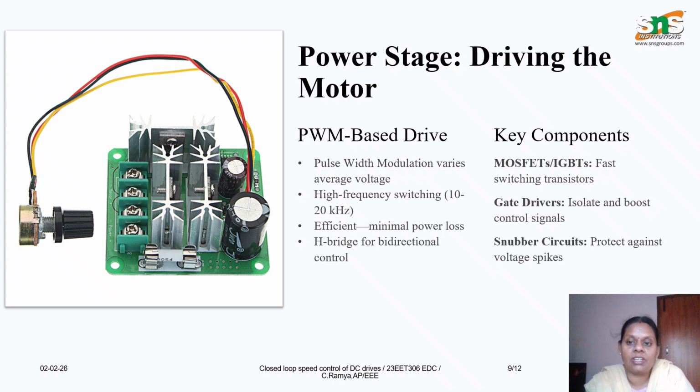The key components are MOSFET or IGBT, which switch fast. We have gate drivers, where the signals are isolated and amplified. We have the snubber circuit, which acts as protection against voltage spikes. Then we have H-bridges, which do bidirectional control. This PWM ensures high efficiency as well as smooth voltage control.